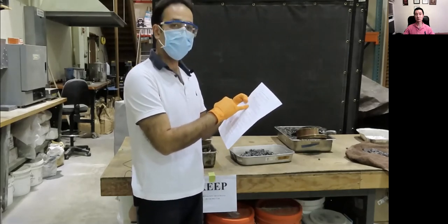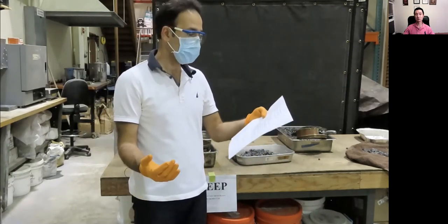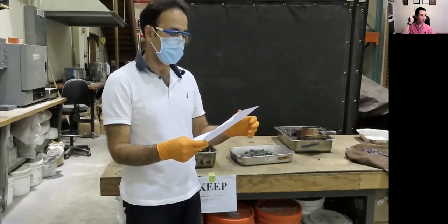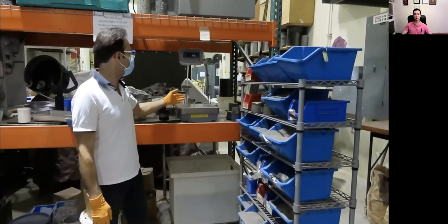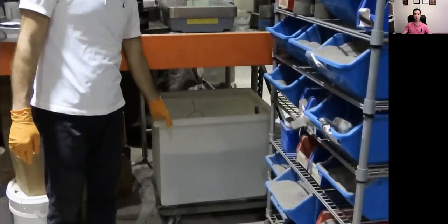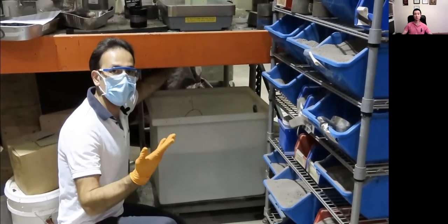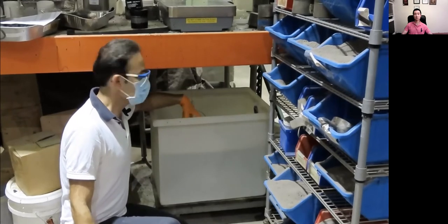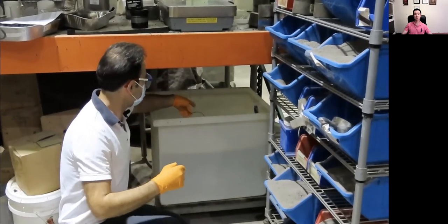And then we need to go to the specific type of scale. It has a water tank underneath to measure the volume of the aggregate. I'm going to explain it there. So let's go to the scale. Okay, for this part I need a scale. As you can see, it's a normal scale. The only difference is that I have a tank full of water underneath, and it has a hook that's connected to this underneath of the scale, and whatever material we have in this part, the weight is going to show on the scale. So what I'm going to do is